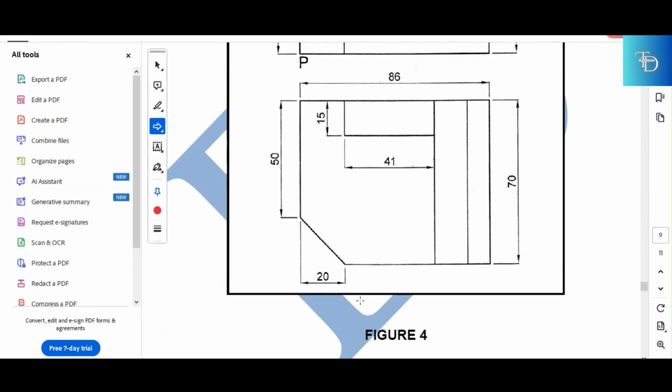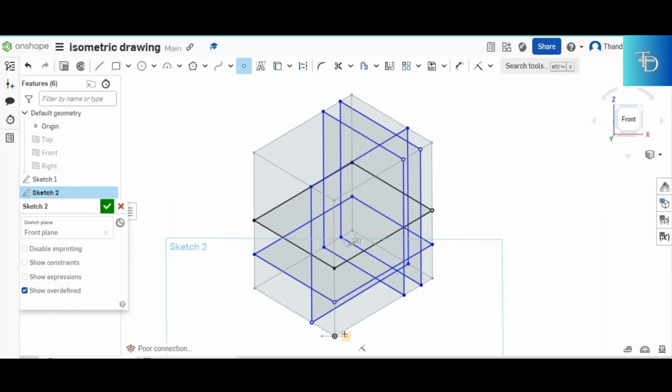And then you come back and take the last outer dimension, which is 20 millimeters from the front side. You take your ruler, you mark 20 from the lowest point. You have 20 millimeters there. And then the next thing, you transfer the dimension. It goes up, it touches the last border, it goes straight down, it touches the other, and it goes back right where it started.